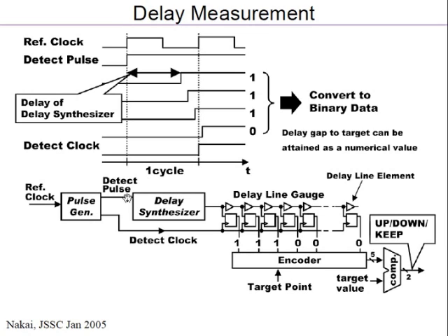So what you have to do is you launch the pulse, and then when the pulse comes out, you have to measure 50% to 50% delay. If you were to do it in simulation, this is what you would do, right? You will see the pulse going in, you see the edge coming out, and then you measure 50% to 50% in the oscilloscope or in the graphical tool, whatever. But how do you do it in hardware?